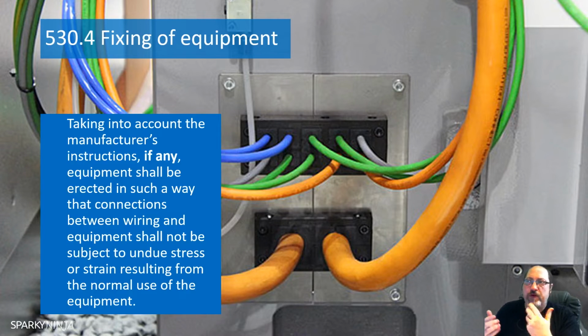Now, obviously, I've done work in homes and sheltered homes where there have been people that are vulnerable and regularly can damage property. When I've done periodic inspections, I'll always assess for that, and I'll always ask the clients about any direct attention to electrical accessories, luminaires and things like that. But most often, they're talking about doors and walls and stuff. But if it has ever happened, then they do upgrade that category. We mustn't select equipment where its use in normal conditions will actually diminish its life.